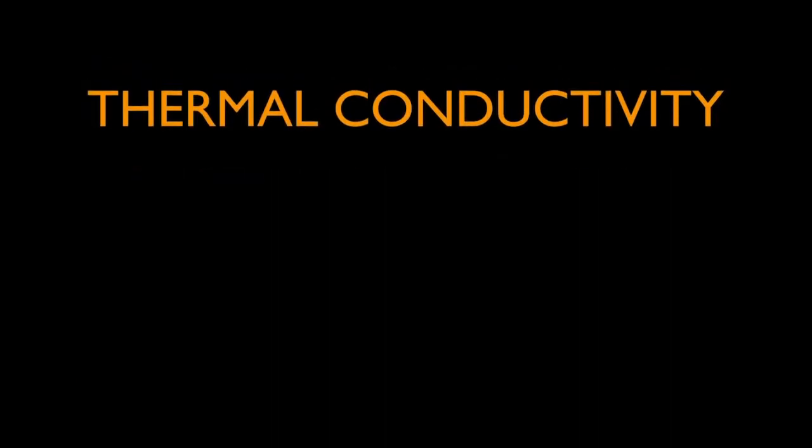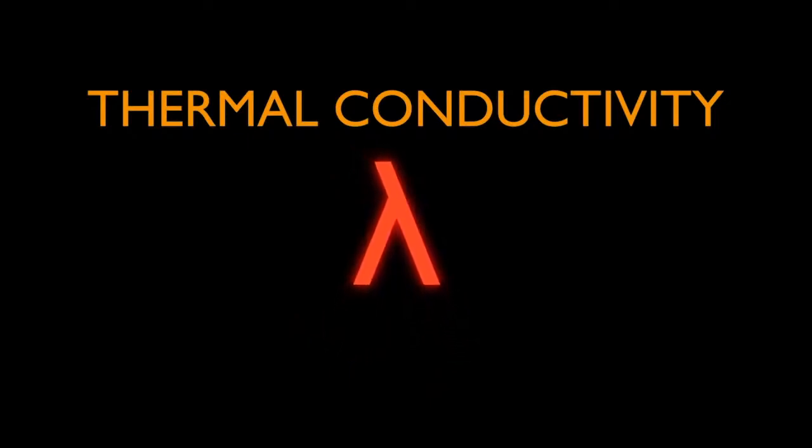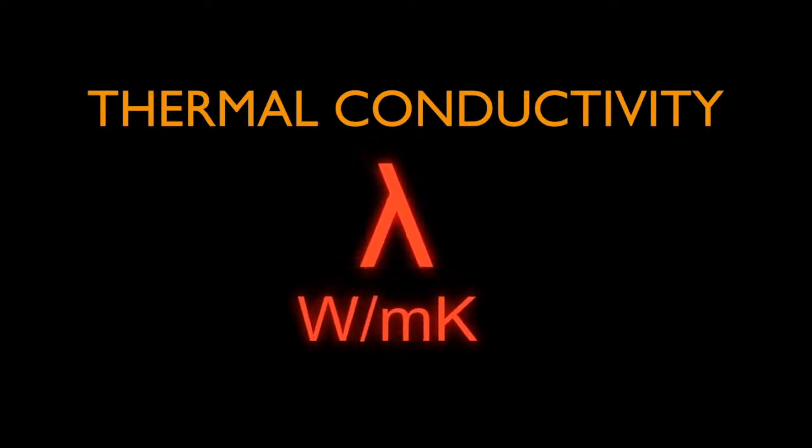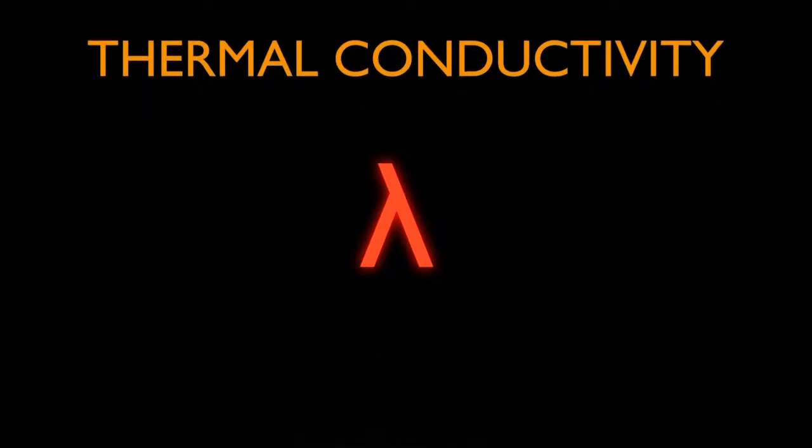Thermal conductivity. The thermal conductivity, also known as the lambda value, or K factor, is measured in watts per metre Kelvin and tells us how well a material lets heat flow through it at a given temperature. The lower the conductivity, the better the material will restrict heat losses.